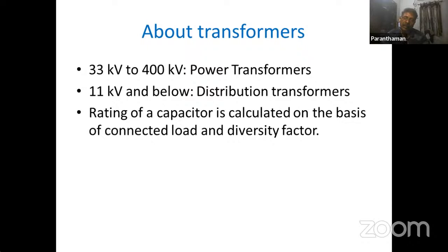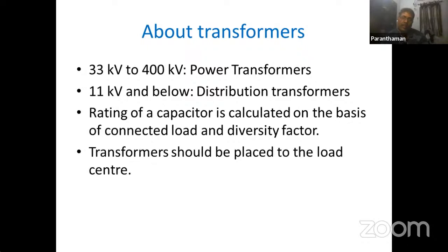That's why the diversity factor is used. For calculating the capacity of a transformer, connected load multiplied with diversity factor will be used. Transformer should be placed at the load center. Why at the load center, sir? This is one important point, sir. Transformer should be placed at the end of the load.